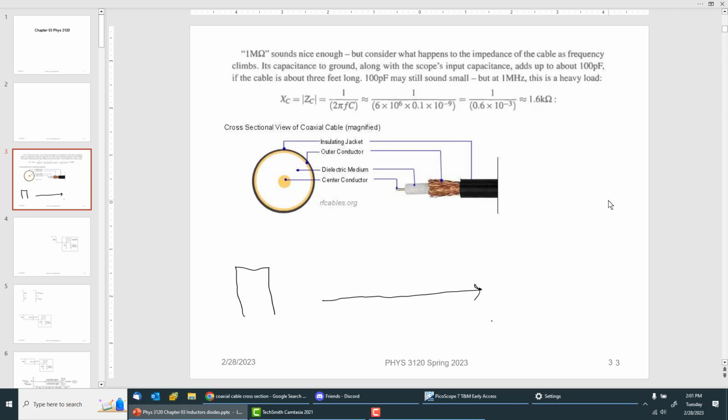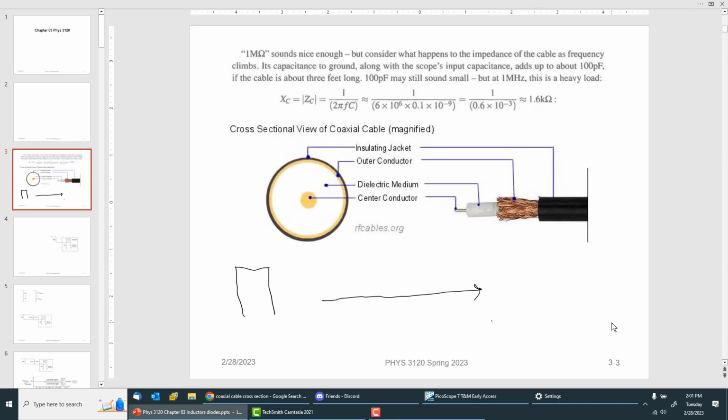Okay, so it started out by talking about stray capacitances and just capacitance. And so our scope probes are 3 feet long. That's why it says that in the textbook. And so this is our first detailed look at a coax cable. There's a central conductor, some dielectric, which is usually Teflon, that whitish looking stuff, and then there's the braid and then the outer insulation.